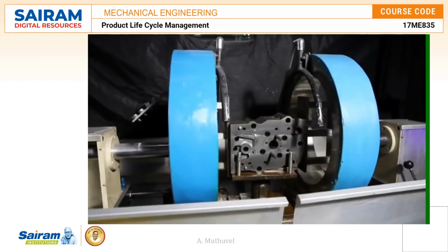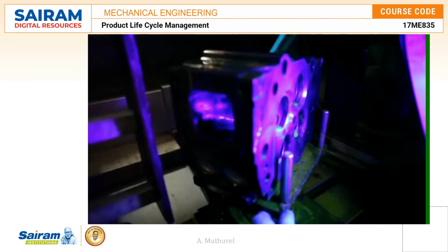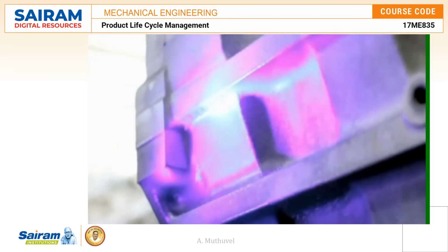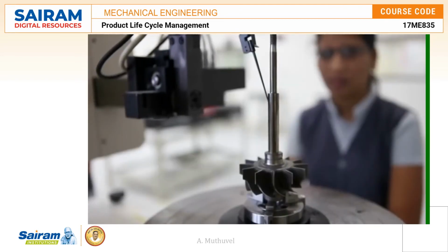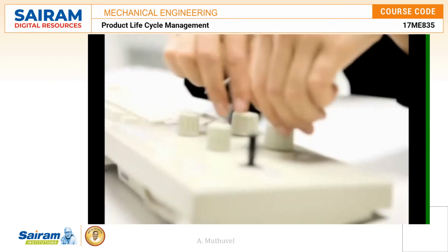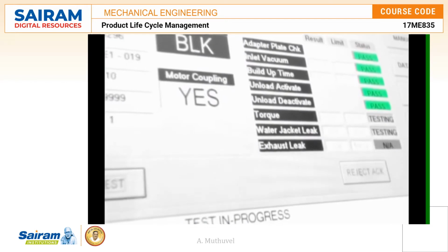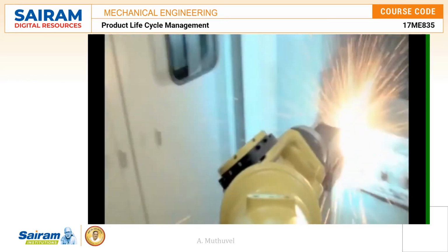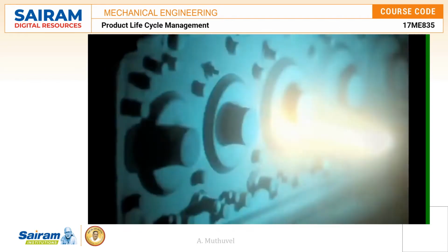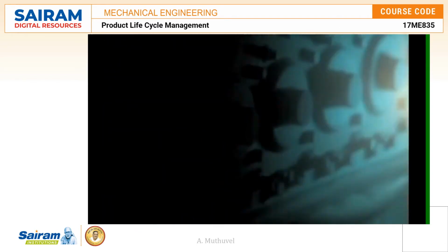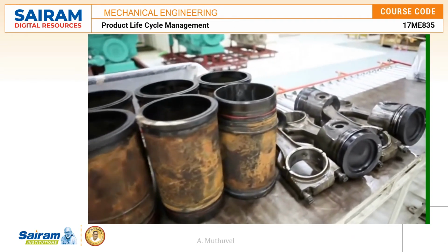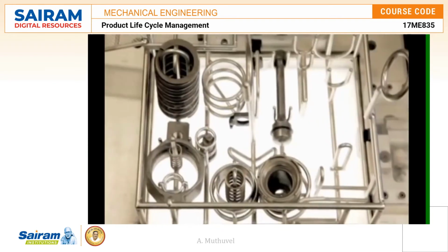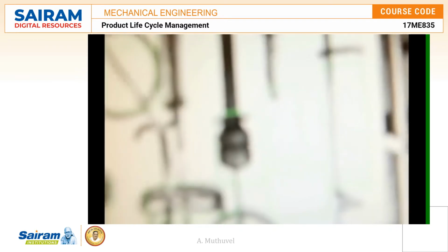Sophisticated inspection processes such as magnetic flux crack detection are used to detect cracks invisible to the naked eye. The out-of-specification parts are remachined using salvage technologies right from traditional methods to advanced processes such as thermal spray and laser cladding. Any part not meeting the original factory specifications is scrapped and replaced with a new genuine Cummins part.